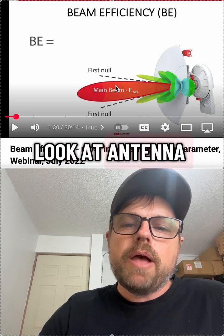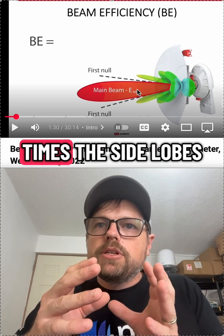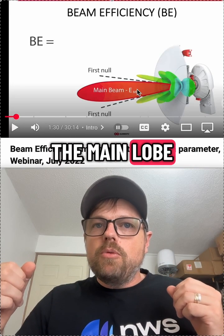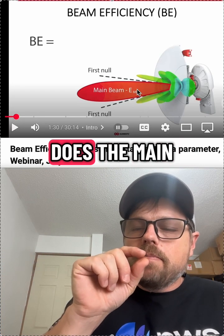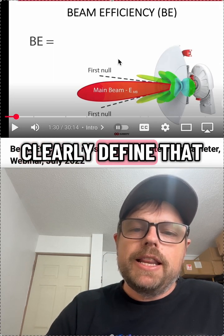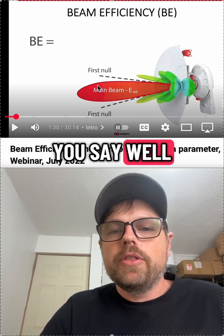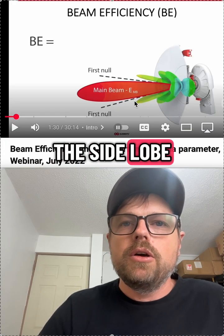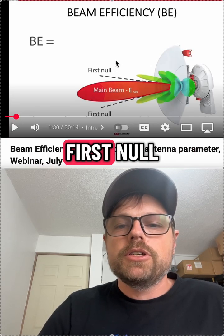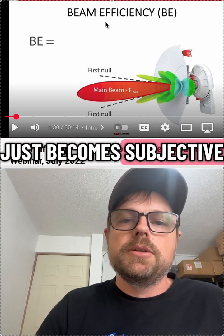So when you look at antenna patterns, especially across a frequency range, you'll notice that a lot of times the side lobes, the largest side lobes, emerge from the main lobe. At what point does the main lobe end and the side lobe begin? If you don't clearly define that, which they haven't, then that's a subjective measurement. You say, well, to me it looks like this is the main lobe and that's the side lobe, but who's to say? You need to clearly define what is the first null. Without clearly defining that, then beam efficiency just becomes subjective.